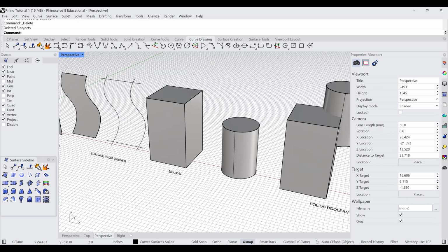If I select on snap on, I can snap to a variety of different things, and I can control that right here. So if I select the end of something, I'm going to go back to my tool. The end or corner would be this little piece right in here. And I have end snap on. So I could select the end of that line, and it's coming down here, and I can select that. Or let's say I want to click to the end of this little line over here. It will select that, and it'll tell me the end.